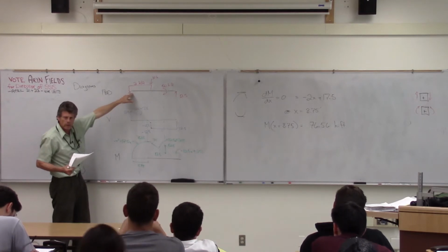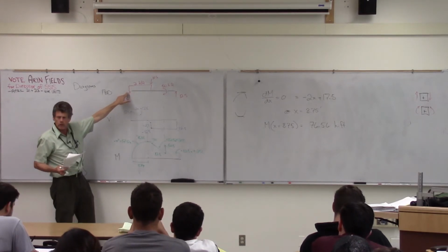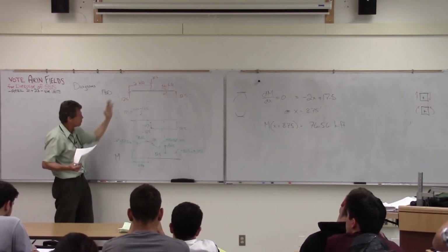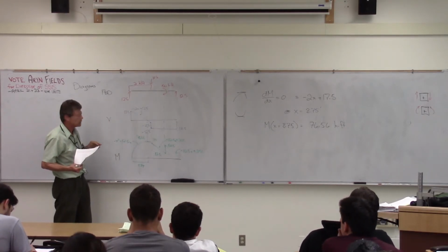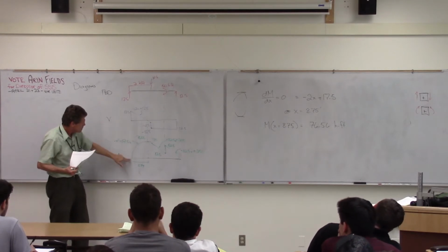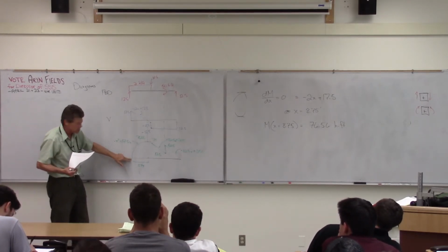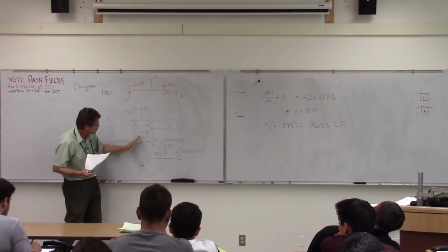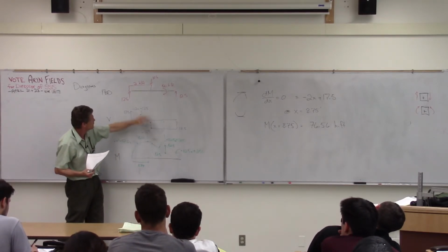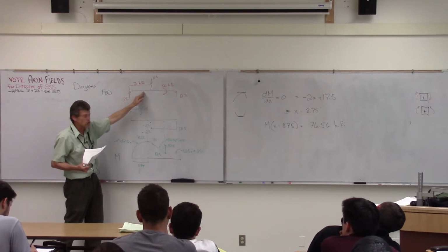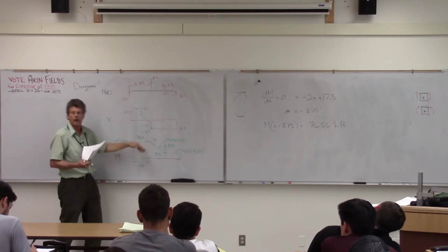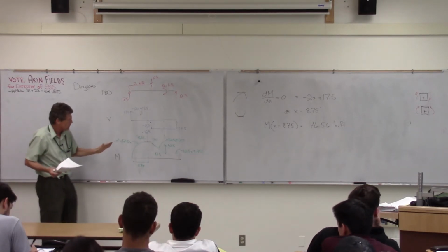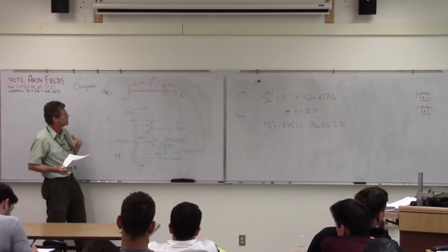So we start here. Notice that there's no concentrated twist here. It's not a frozen, it's a pin. So it's basically going to be free to deflect however my loads tell me it wants to move. So basically what it says is my moment is going to be equal to 0. As I'm moving along here, it starts going higher and higher and higher to a point here where now this distributed load is starting to take over and saying, I'm going to twist you in the opposite sense there. So I reach a max at 8.75, and then I start coming down to the 7.5.